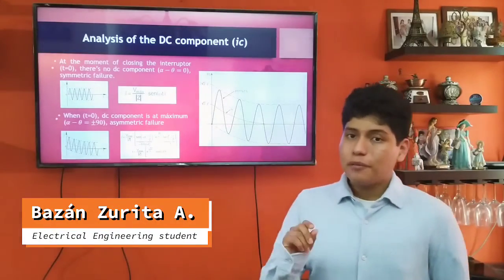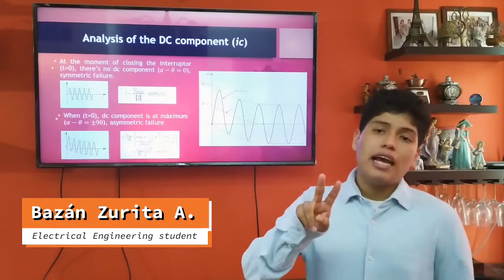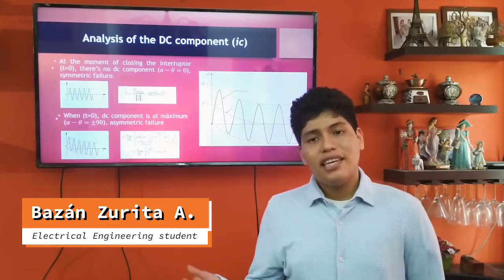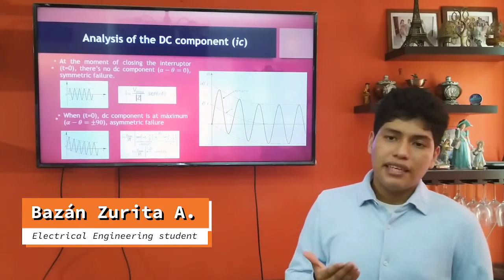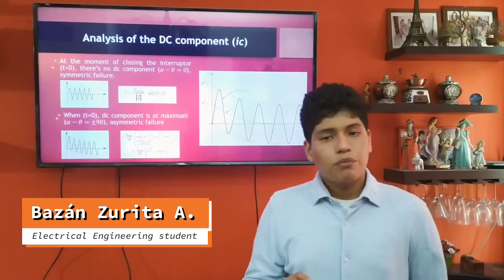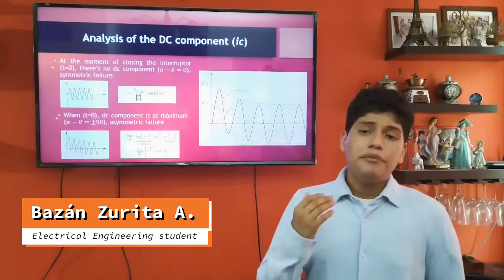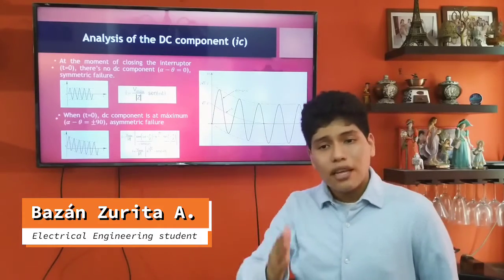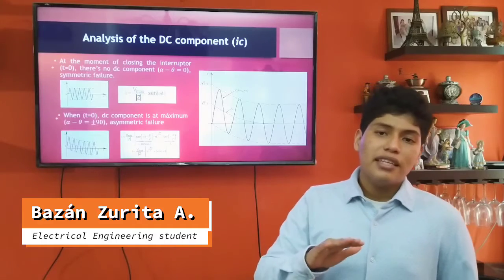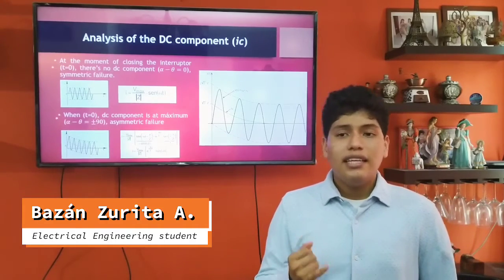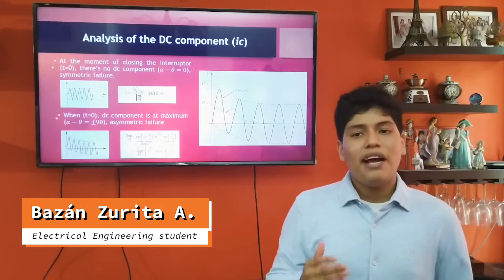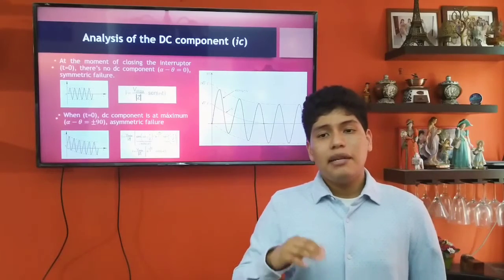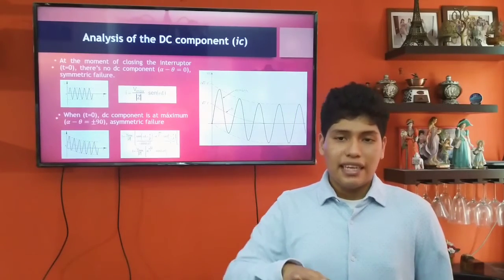As highlighted at the previous point, the short circuit current has two types of components, DC and AC. But before going into detail on these characteristics, it's worth highlighting two behaviors present in the proposed electrical grid. The first is stable behavior, which is obtained when all electrical variables, current or voltage, exhibit a constant sinusoidal behavior over time. Conversely, the second state, called transient, is the one where electrical variables tend to vary over time and the sinusoidal behavior is altered, until it reaches a stabilization point of the aforementioned state.